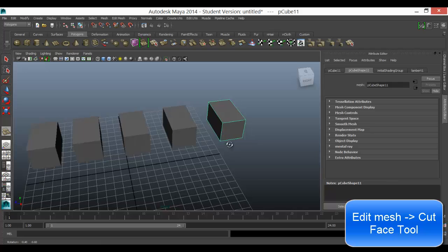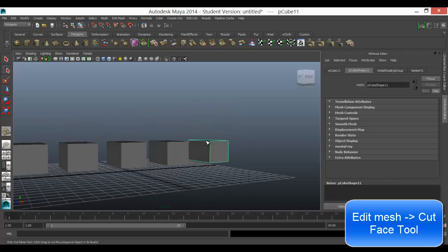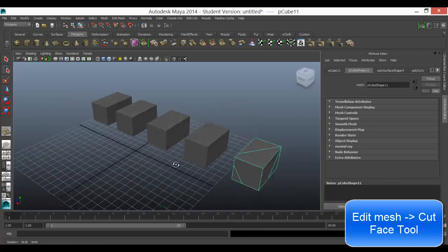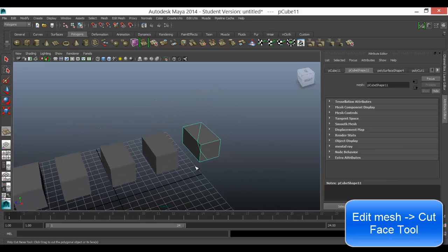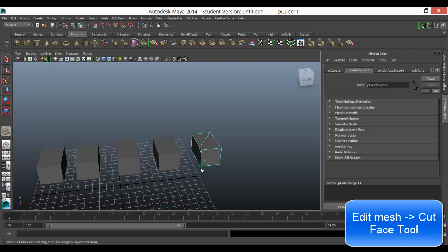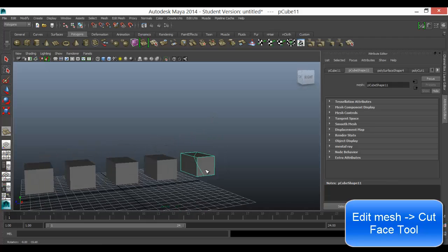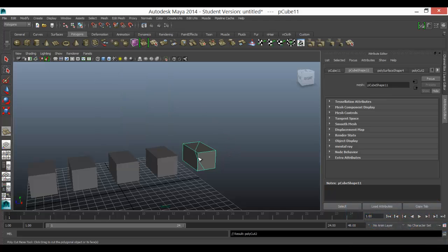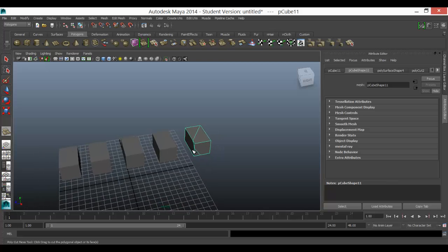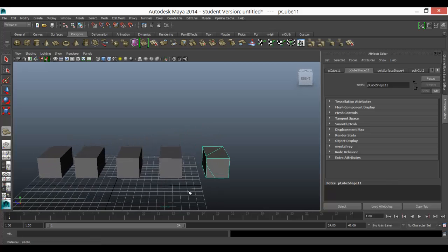This is the Cut Faces tool, and it's really important where the camera is, and I'll show you why. I click and I rotate round, and I can angle to divide this shape up. There we go. Now what that does is it cuts through from the angle of the camera, so you can see that division is really quite strange. Now that's made a lot of funny 5-sided shapes and 3-sided shapes, but what it has done for me is it's divided it in a particular way straight through the surface. So if I was going to then delete part of this surface and fill that hole, I could do that. The Fill Hole tool is just in here in Mesh, and then I could tidy it up a bit afterwards. So it's a good way of getting a division in a slightly more unusual or organic way.